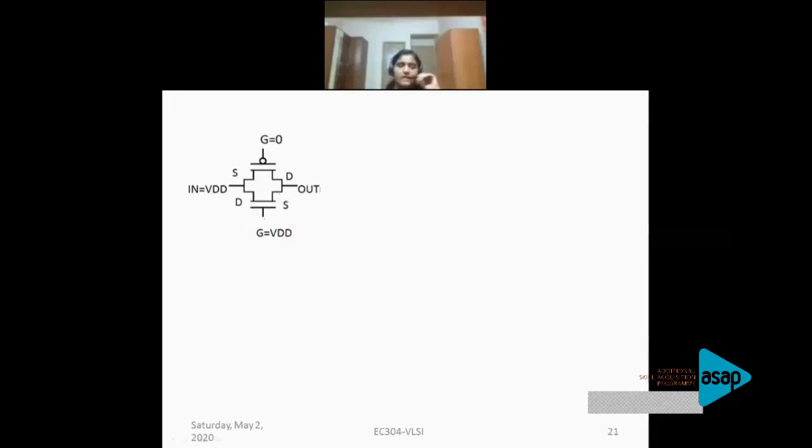So we'll start by analyzing the NMOS first. What are all the regions of working the NMOS goes through under this input condition? So that we do not forget, I've also copied the linear and saturation region equations. What terms are here? There are three terms: VT, VGS, and VDS. VT we can choose as a standard value, around 0.7 volt. Now what is VGS and what is VDS? We need to write an equation for both depending upon this particular circuit.